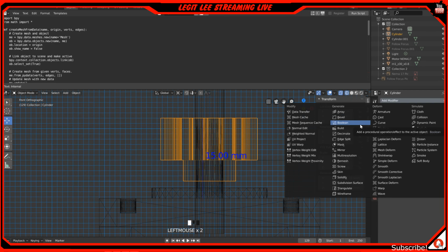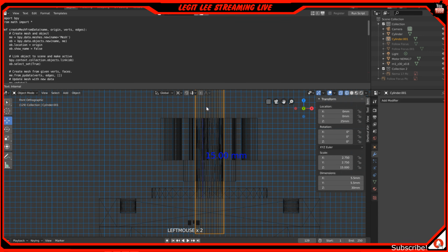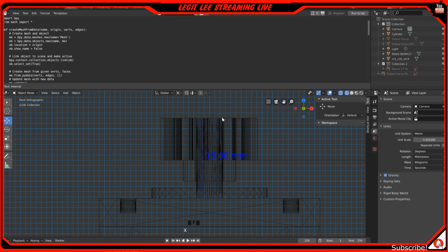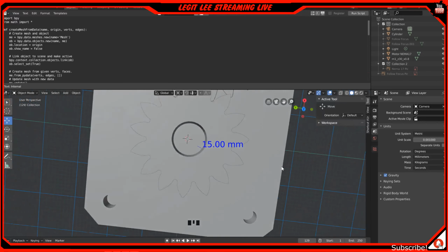This time we're going to click on the gear, hit Boolean, grab this eyedropper, click on this guy. We're doing a difference, so that's what we're going to be doing here. If we hit apply, that'll be it. We can delete this one, hit X, and then if we do solid mode, you can see we got a hole all the way through that allows our shaft to go through.